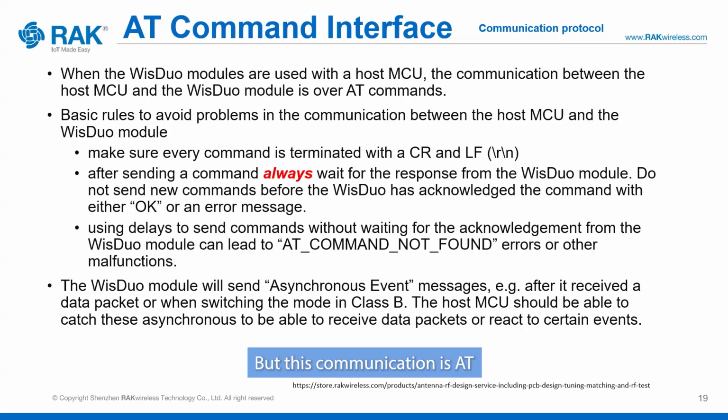But this AT command interface is a communication protocol. There is one way towards the WisDuo module, and the WisDuo module will always acknowledge the command or give an error message. And during the communication, it's very important that after sending a command, the host microcontroller should always wait for the response.